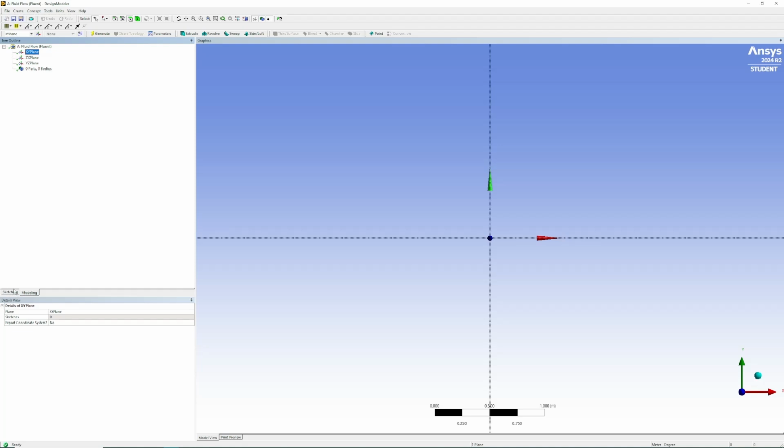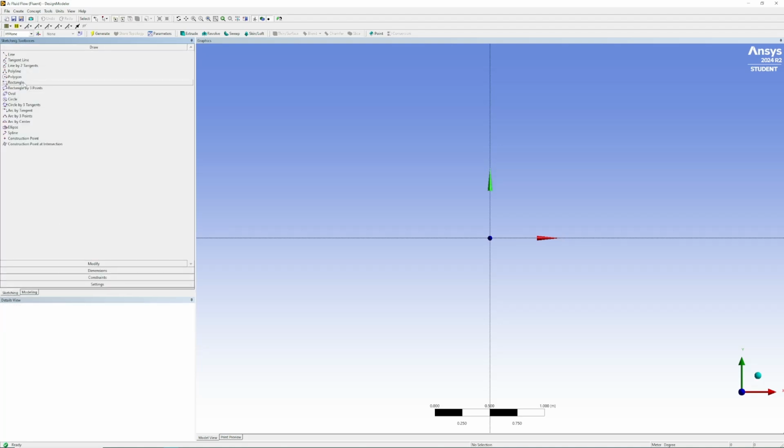I'm selecting the sketching tools and I'm going to draw a rectangle. I move over to the point, which is the origin, so you can see the symbol changes to P. I'll do one click. I'll move my mouse away and do my second click, and now we've got our rectangle.